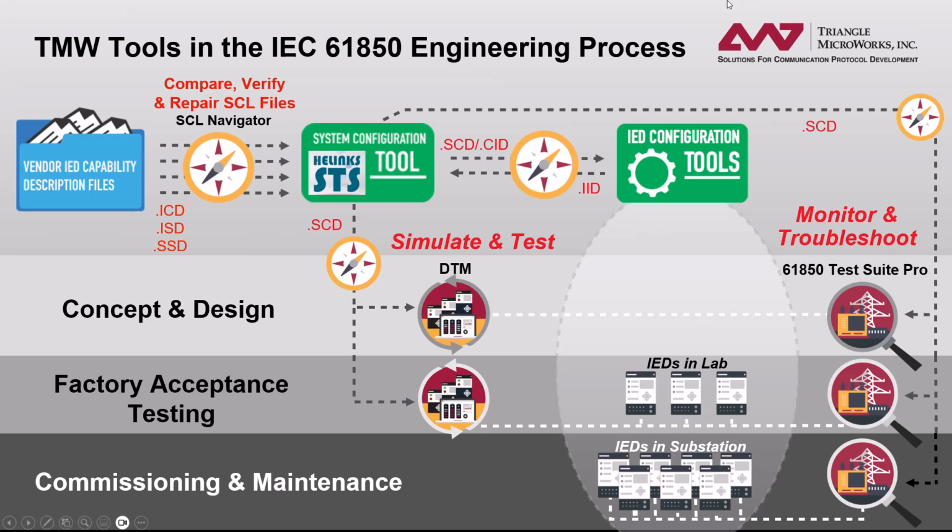During the conceptual and design phase, you can use a configuration of 61850 devices for Test Suite Pro to create automated tests to test your system. These tests can be reused during the factory acceptance tests when you have some IEDs in the lab, and during the commissioning and maintenance phases when all of the IEDs are in the substation.